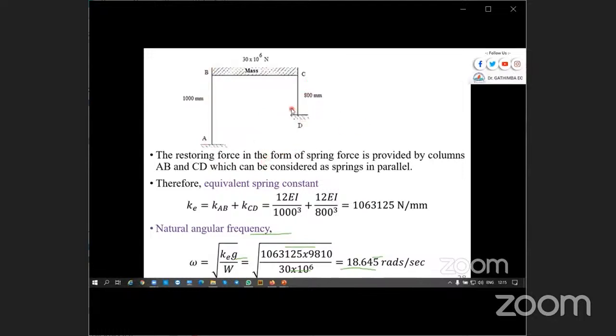And we need to first get the equivalent stiffness because for our body, you may have a frame structure like this, no matter how many floors you are considering. But our dynamic system will be represented using a single stiffness like that. So you have the mass at this level, the mass at this level, and all that. So we need to get this equivalent stiffness at each of the 4 levels.